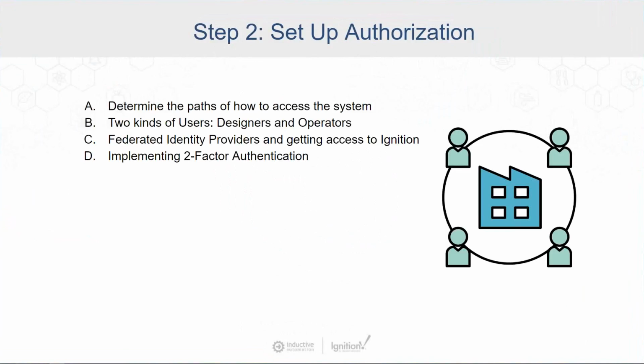And you are in complete control of what authentication systems you want to use and how you want to lock those down. But one of the great parts about Ignition 8 with Perspective is that we now have the ability to use federated identity providers. These are providers that provide a single source of truth for the users. It's one place. This is where we're all used to Active Directory. Active Directory was a great way of having a single source, and all of our computers and applications can use LDAP to query into that. And that's a great way.